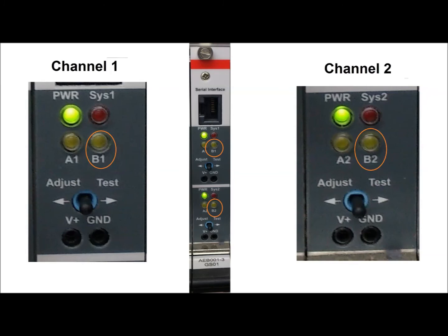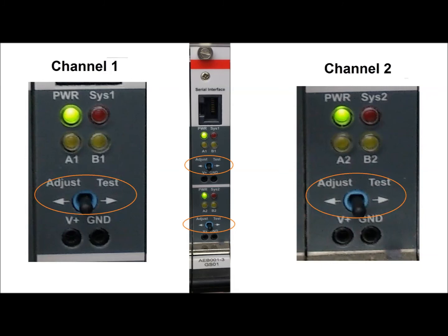The toggle switch for System 1 or System 2, when pushed to the right, will simulate a dampening of the wheel sensor. Care must be taken to avoid accidental operation of this switch because some sections will become occupied. Both toggle switches are operated together, firstly to the left and then to the right in the correct sequence, which will activate the electrical calibration of the wheel sensor.